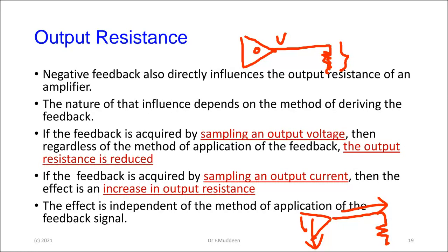Conceptually, that's the operation and importance of the output impedance. It's a question of how much of the voltage or current appears across the load. In both cases, you want to maximize what the load is getting. That is the whole purpose of the amplifier, not to keep this stuff inside. It's kind of like happiness. You don't want to keep it inside, you want to spread it out. So you need a low output impedance for happiness.